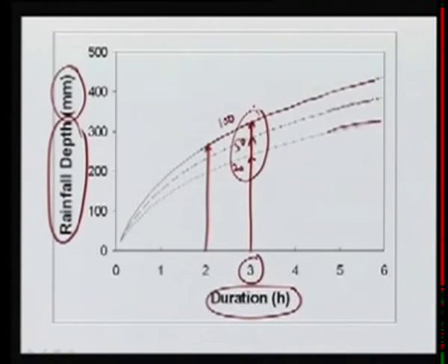So in today's lecture, we have taken some examples and analyzed the behavior of precipitation over an area. We have seen how to estimate missing data for some stations, how to check the consistency of the record at various stations, and how to compute areal averages from the point rainfall values in order to get areal average precipitation from a few rain gauge measurements.